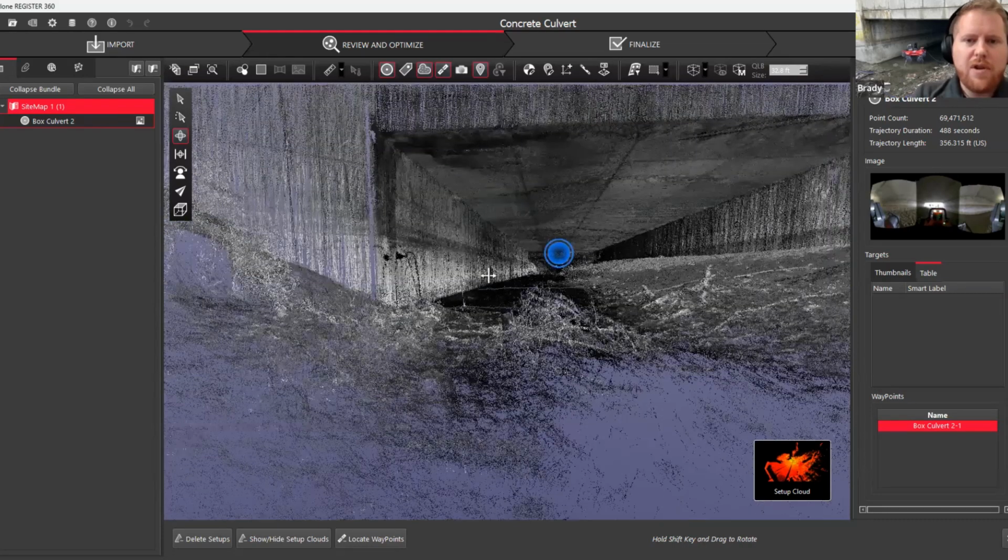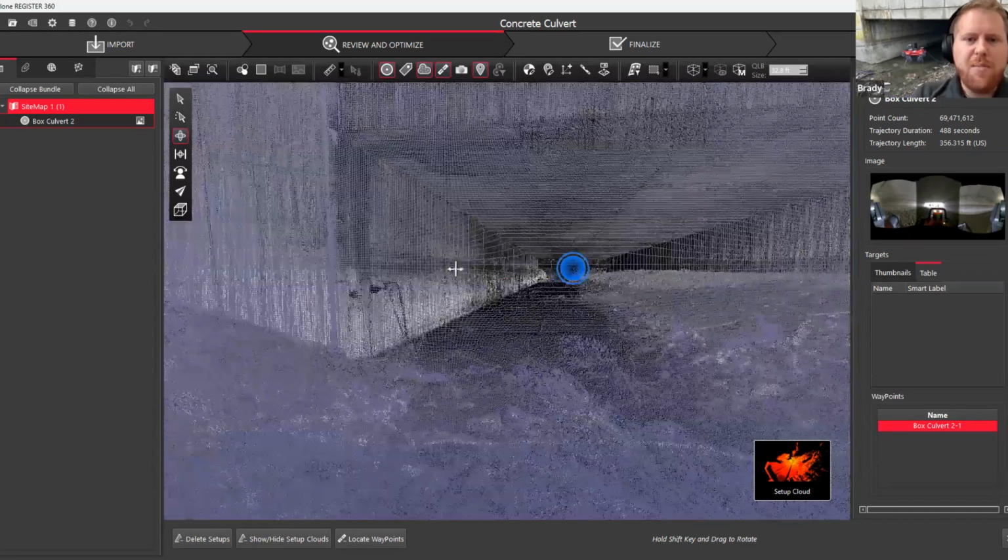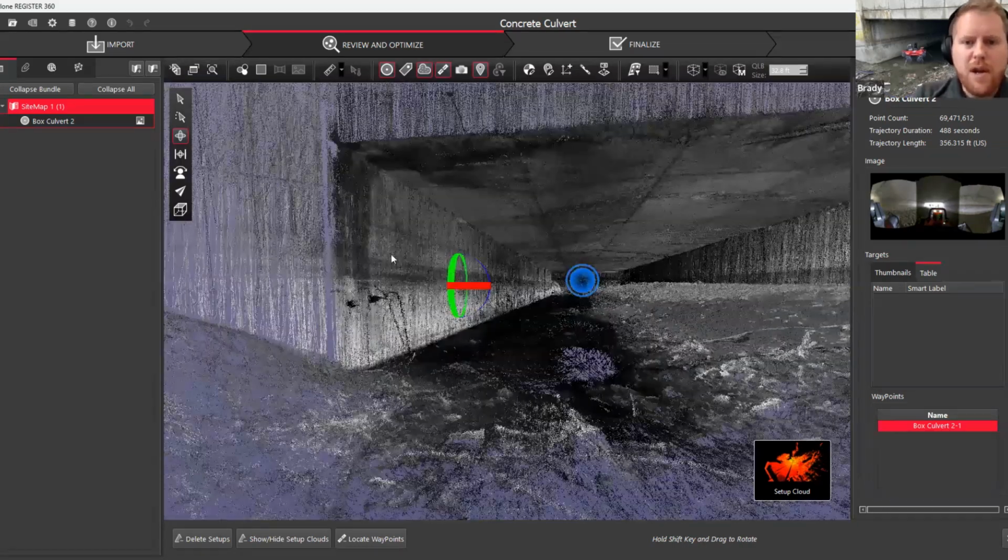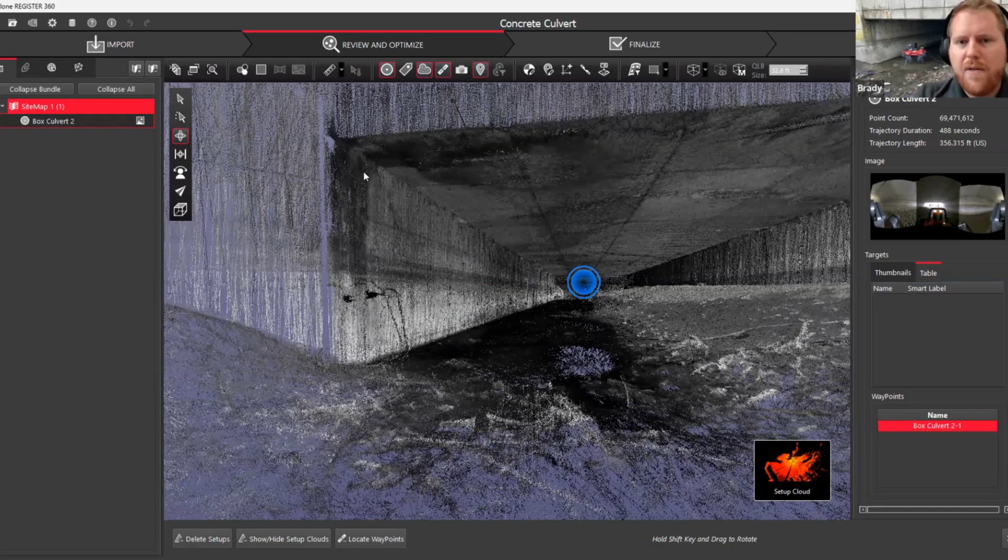As we move in, I want to direct our attention to this upper left corner of the culvert. What we can see is there's a lot of color change right here. This is indicating that there is actually water penetration or something seeping through the concrete itself in this culvert, which means it's not retaining the water the way that it should be or keeping other water out of this potentially toxic water source.